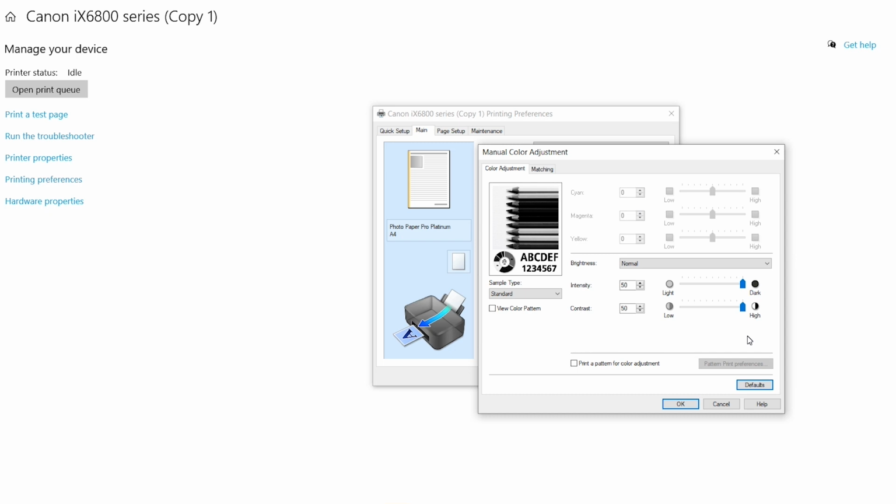As I said, if you do everything right, then 10 mils you can do with confidence. Actually, with an elaborate process, you can do 5 mils. But yeah, 10 mils with confidence. And 10 mils is what we want.